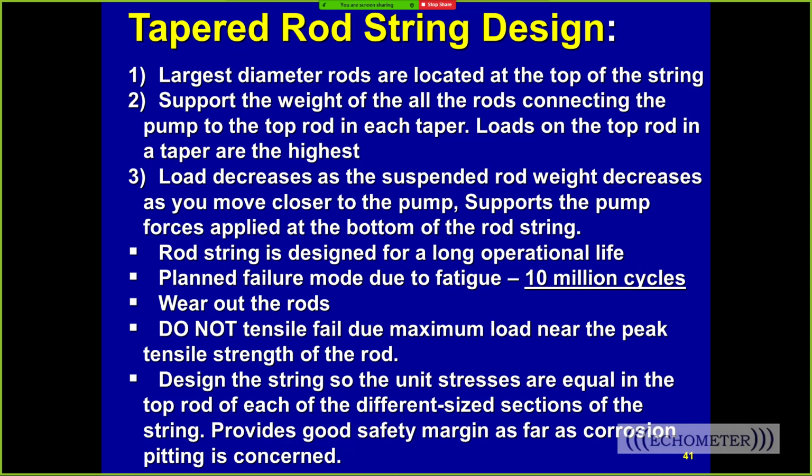Any other questions? Yes. One more question here is probably a statement that we should do at the beginning of the presentation. The QRod works for vertical wells. And the question is, does QRod serve as a good estimate for pumps that are pumping from the curve in a horizontal well? And the answer is probably as good as anything else. And so that's not a very good answer, but there's a lot of problems right now with the other programs that are design programs trying to predict the mechanical friction due to deviation and dog legs. And so what I'll usually say is just use a true vertical depth for the rod string depth, and that will work just fine in QRod.